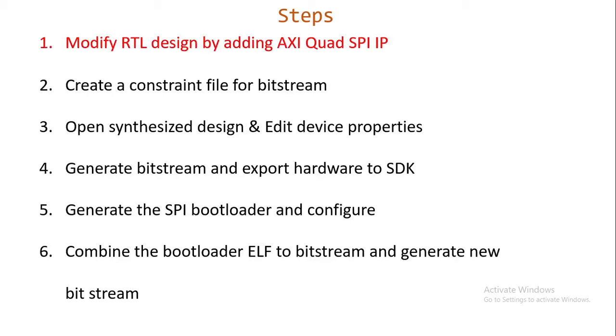First, you need to complete your RTL and processor application development and test the complete functionality by downloading it into the board through the JTAG interface. And once that functionality testing is completed, then you can start the first step for putting your application onto the non-volatile memory. So I am assuming that you already have a working RTL and the corresponding software application ready.